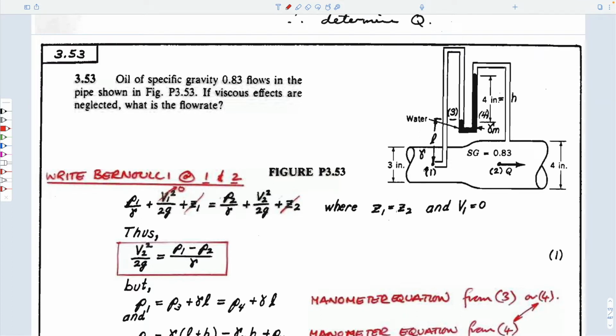So an example where we have water flowing in a pipe, kind of a Venturi meter, has a different diameter here from here. It truly is measuring the differences in pressure in an upstream location where it's slimmer and a downstream location where it's wider. I guess it's not water that's flowing. It's something that has a specific gravity of less than that.